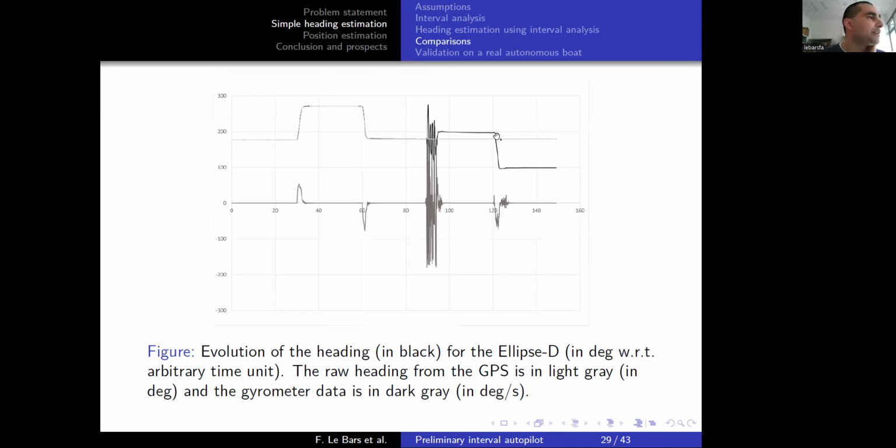And then when we move back the magnetometer part to the initial position, it sees the movement, and we see that there is probably a difference of 90 degrees, which corresponds to what we did. We moved from the west back to the south, but it's still not the correct value, because we should be towards the south as the GPS is saying. So we have a big problem here.